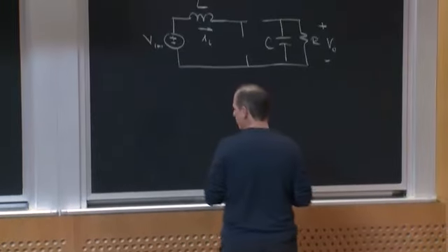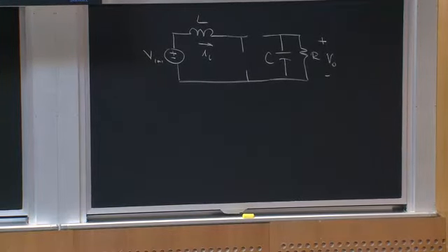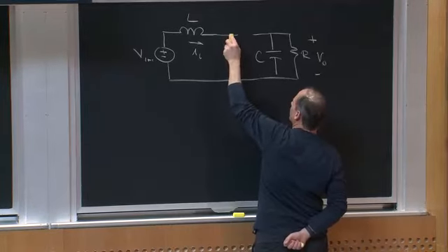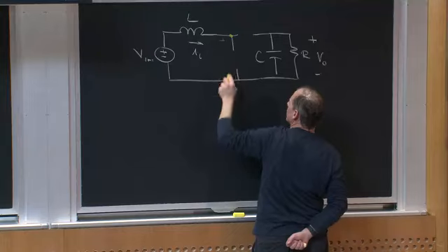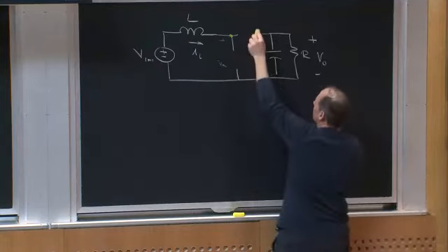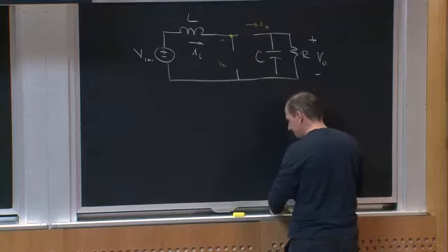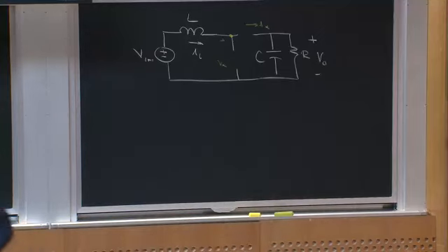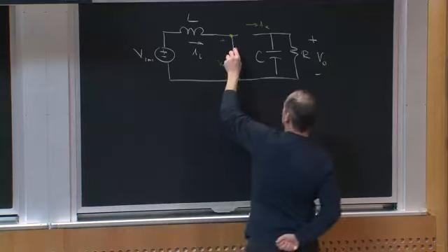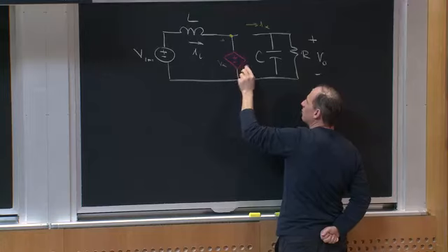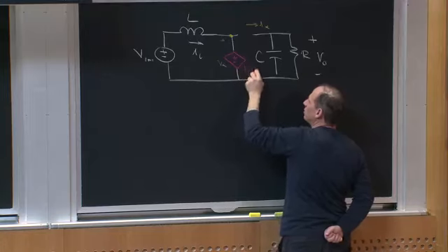And here's how I'm going to argue, and there's a couple ways I could do this. I have to worry about the voltage Vx here and the current Ix at this node. Maybe I would model this as a dependent voltage source. So what would this voltage source be? I could write this dependent source as 1 minus Q times V out.